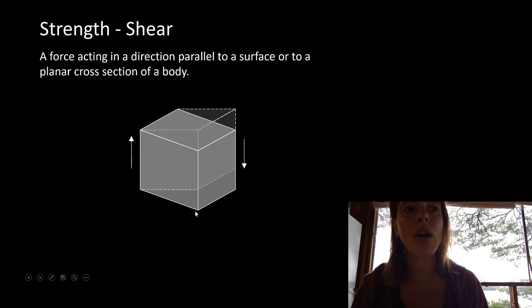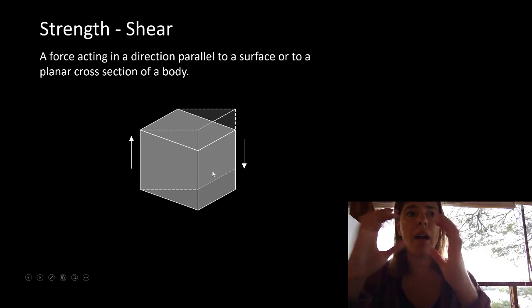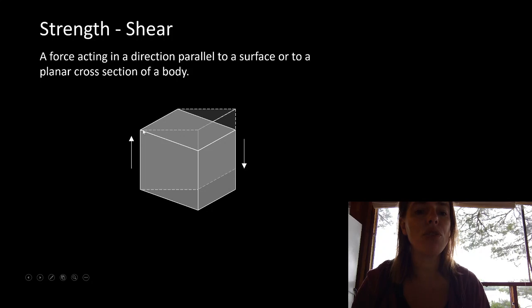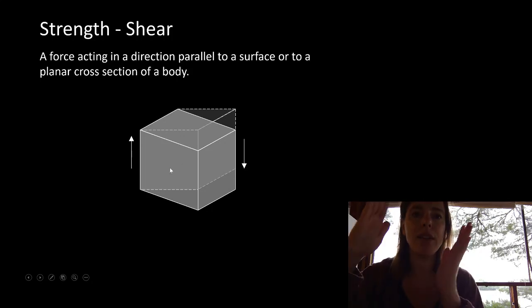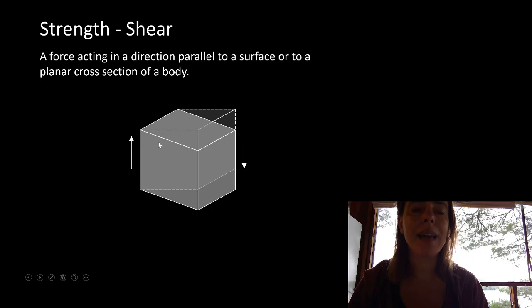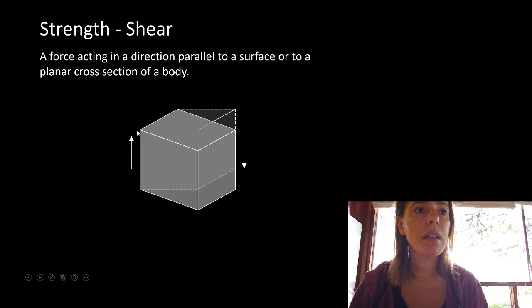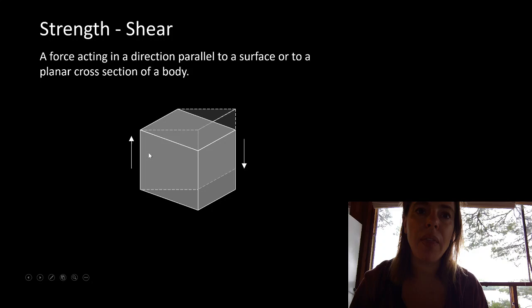If you guys remember that concrete cracks along a diagonal kind of going up through the system, you can see that what we've taken with that square is that this distance here has tried to stretch out, and this distance here has tried to compress. So we've basically changed the plane a little bit, and we're getting tension across here and compression across here. The reason that's interesting in the concrete one, you guys remember that concrete is kick-ass in compression, but crap in tension. And look, you can see this act of shearing here is causing tension along that line, which is why we would get cracks going along that direction right there.